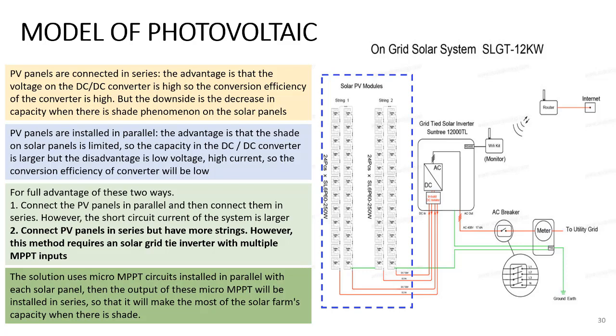When the PV panels are connected in series, we get a higher voltage and a smaller current, so that the dissipation could be reduced and the working current through the inverter is small and in the safe range. However, if a shading phenomenon occurs over the panels, the overall efficiency of the PV system is reduced very fast.